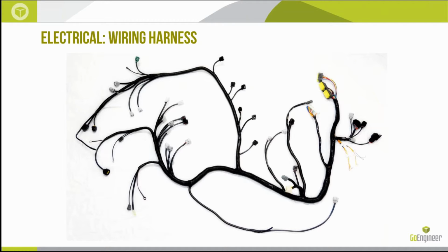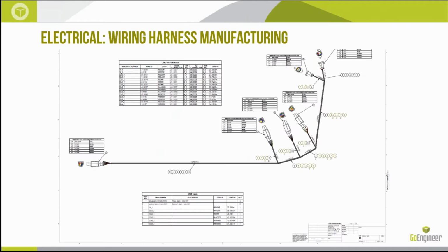So this is the big show here: these two things, panels and harnesses, are almost completely separate. They're almost mutually exclusive with their needs. Here we're not doing anything that mounts on a DIN rail. We're not doing anything that wires directly in, usually. There's a couple pigtails on this harness here, but we're generally talking about connector to connector and how we manage that information and how we manufacture that. So that last part, how do we manufacture it?